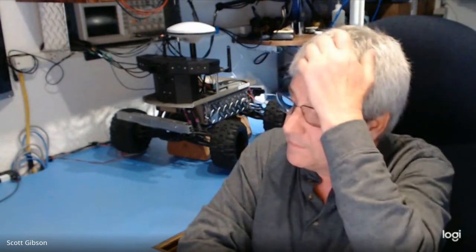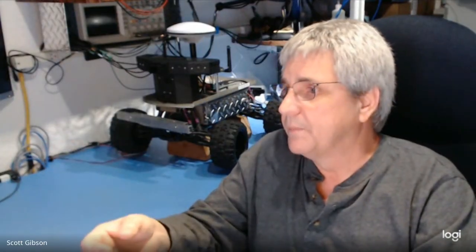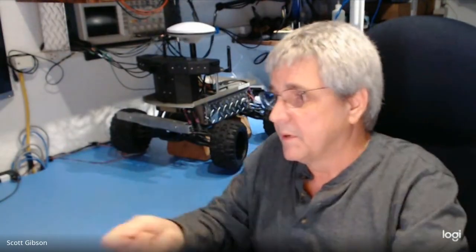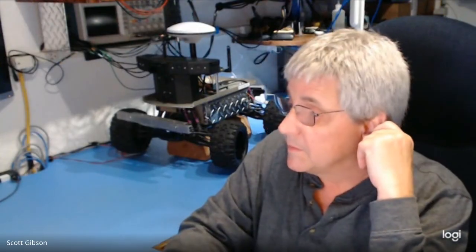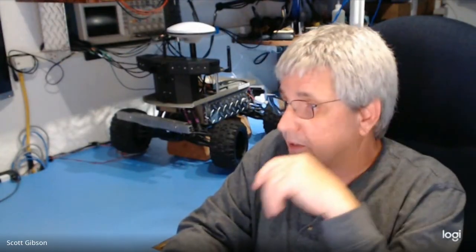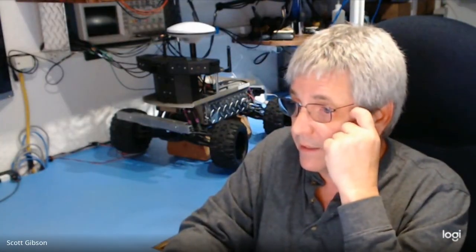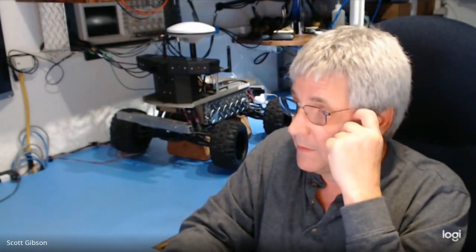I've been really impressed with those little sensors. They're really nice. I wish they had some sort of addressing scheme on them though, because each one has to have its own serial port. I think you can get a CAN version as well that you can set the addressing on, but the ones I have on there are just serial. But you can set them up where you just power them up and it just starts puking data out at you. So the interface is really not that bad.